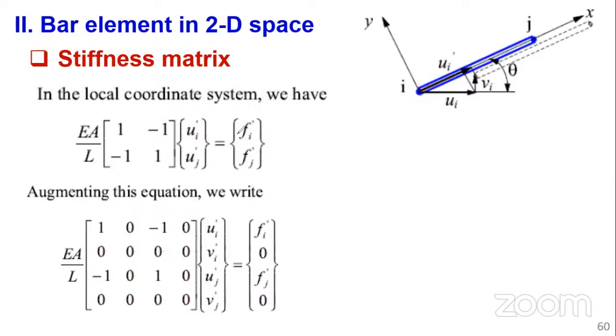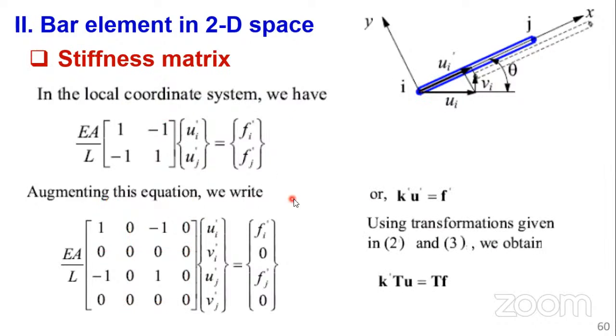So looking at this, our target now is to get the stiffness matrix for the global coordinate system. You see, we have this at local coordinate system. Of course, F is equal to KU. We say any quantity in the local coordinate system can be transformed into the global coordinate system by use of a transformation matrix.